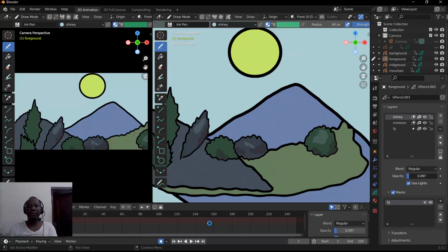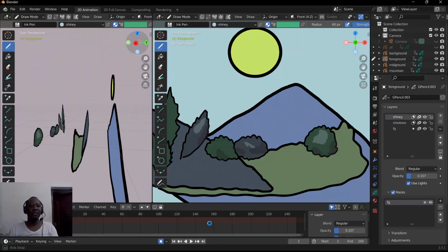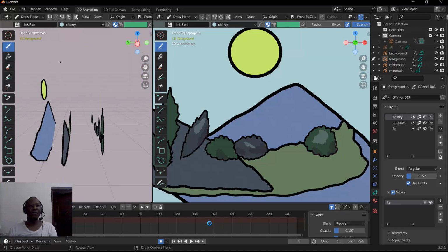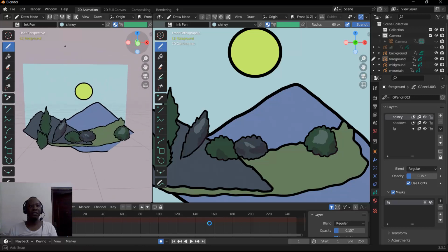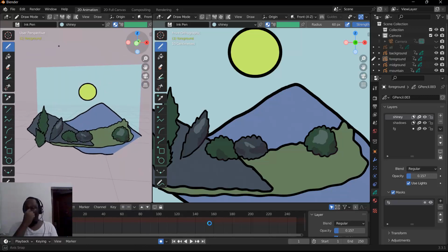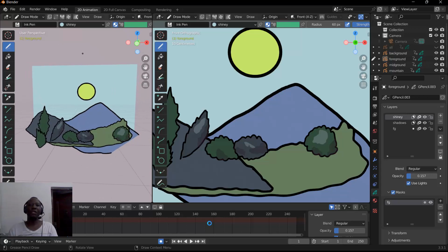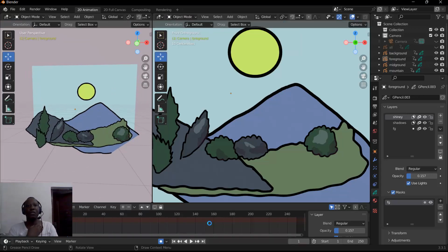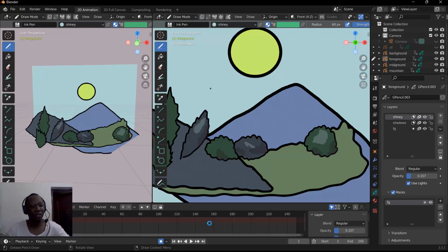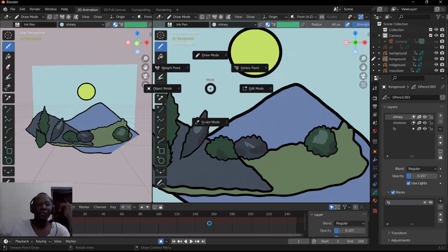But you can actually jump to any layer you want. So if we exit draw mode and go to object mode, actually, to do this you shouldn't always be clicking the draw mode and object mode. I think it's tilde, right? So if you press the tilde key and press 6, you're in edit mode, and 8 you go back to draw mode. So if I want to go to edit mode, I'll do the tilde and then 6, and for draw mode, tilde and 8. So that's the best way to do this.